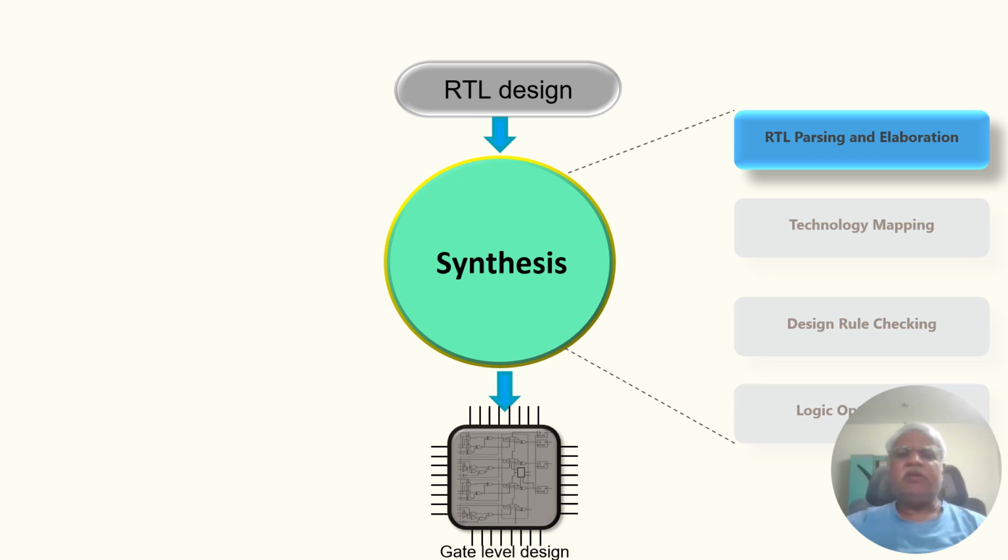This design hierarchy actually will represent the entire design, that means the HDL code of the RTL. If you observe carefully, this design will contain all components, how they are linked and how they are related. All that information will exist in this portion, and this will be ready for either simulation or further synthesis. This is the key step.